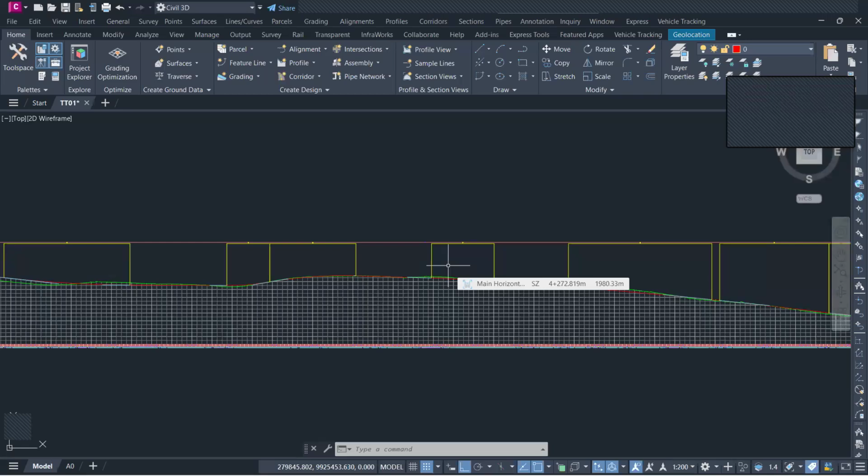So if the CBR was 10, there's a possibility that you're going to achieve a CBR of, let's say, 20. If it was 14, there's a possibility you can achieve even a 26. But one of the shortcomings that you mostly have with improvement of subgrade materials is that you will notice sometimes the Atterberg limits may not be affected. That is, for example, the plasticity of the soil, and all of these. And of course, they are important components when you are looking at this material.